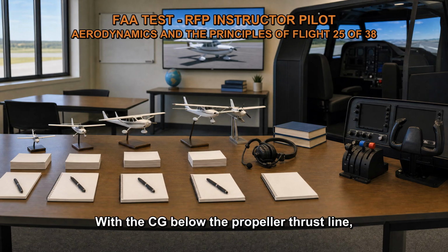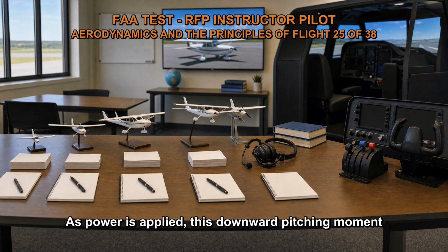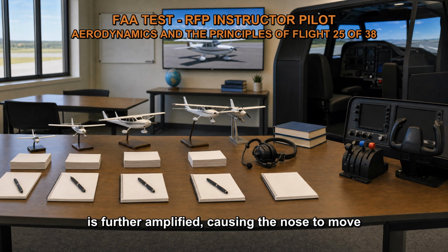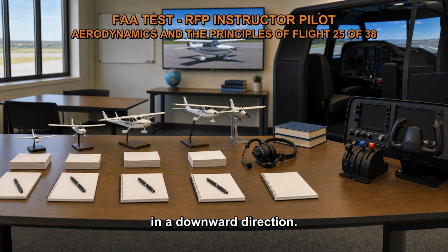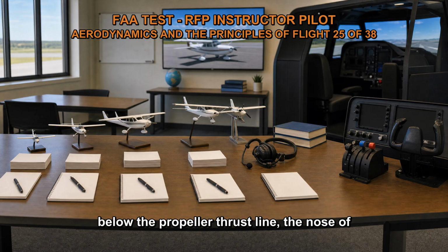With the CG below the propeller thrust line, the weight distribution of the gyroplane is such that there is a greater moment acting to pitch the nose down. As power is applied, this downward pitching moment is further amplified, causing the nose to move in a downward direction. Therefore, in the given scenario, when power is applied to a gyroplane with the CG positioned below the propeller thrust line, the nose of the gyroplane will pitch down.